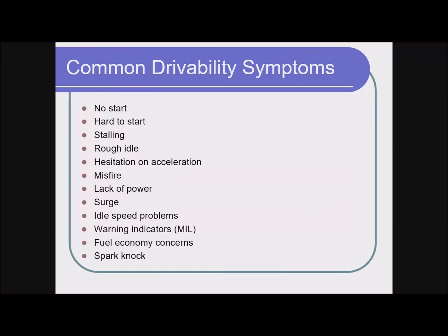I have seen engines, though, that just stop running driving down the road, so maybe it's running at 2,000 RPM and all of a sudden it loses ignition for some reason, or it loses fuel. Maybe the fuel pump dies, right? So I don't really call that stalling. That just quits running, right? Stalling, we're really thinking more when you come to a stop, you're at idle, it idles poorly and then quits running, right?